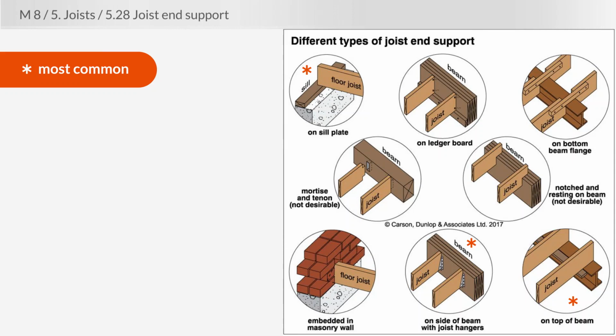At the center left, the mortise and tenon joint, that's very common on homes that are 100 years old or even older. That's considered to be a very desirable connection. It's not done anymore simply because we don't have the old growth wood. And that's a very time-consuming connection.